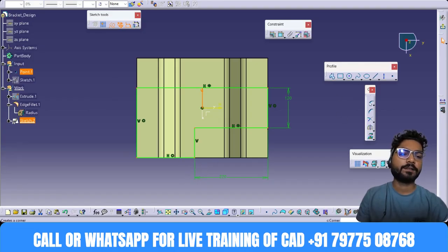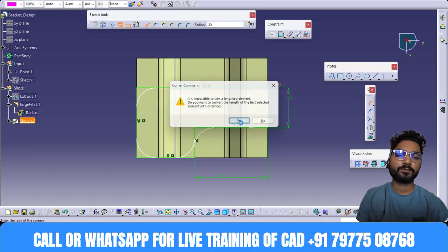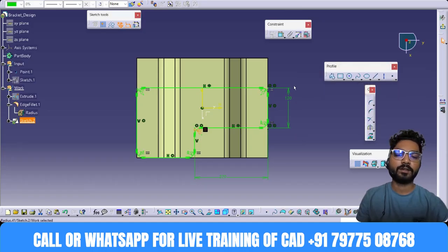Then directly select the corner command, and whatever radius you want, you can give. Let's suppose 25 mm. So all are 25 mm. Once you edit one radius, it will impact all. It is connected, so the formula is applied. Exit now.